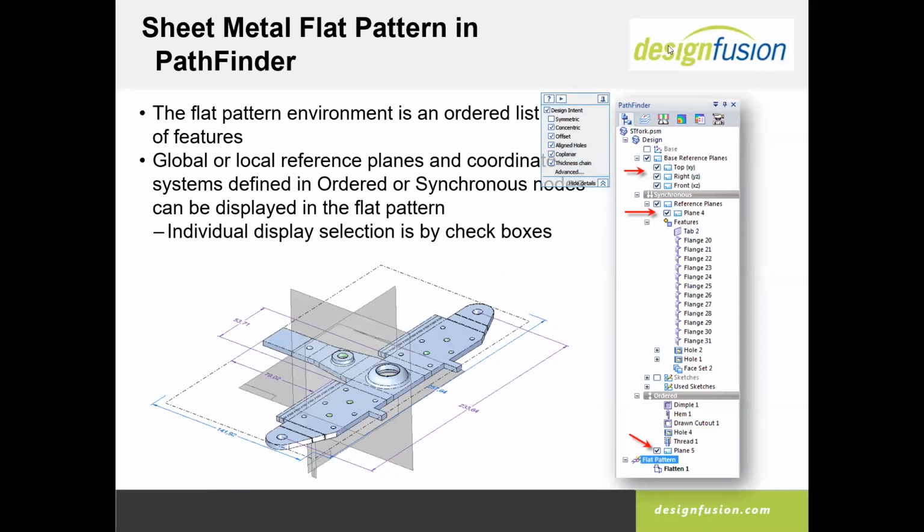Now, also, the flat patterning is inside Synchronous as well, and it behaves identical to the ordered flat pattern. That's because flat patterning always occurs in the ordered paradigm. So we'll show you more about this on Thursday, but notice here we have synchronous features, then we have ordered features, and then we have the flat pattern. Even if you don't have ordered features in here, the flat patterning always occurs in the ordered paradigm. So the basic commands that I showed you yesterday apply in the synchronous sheet metal as well.